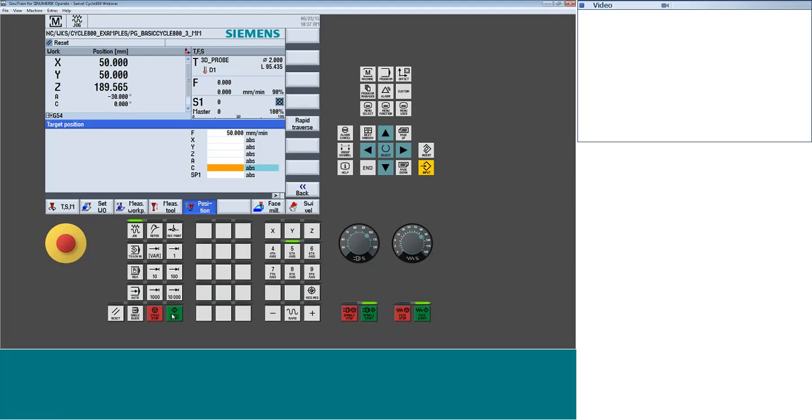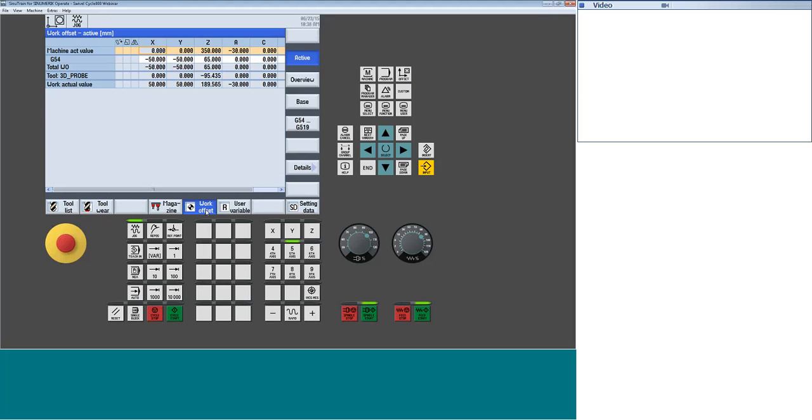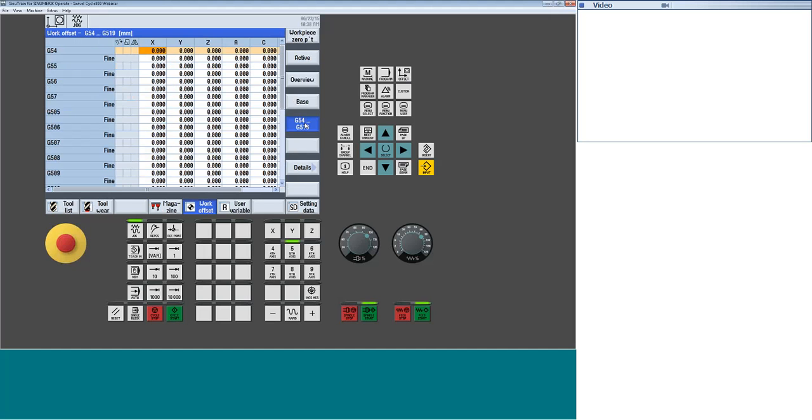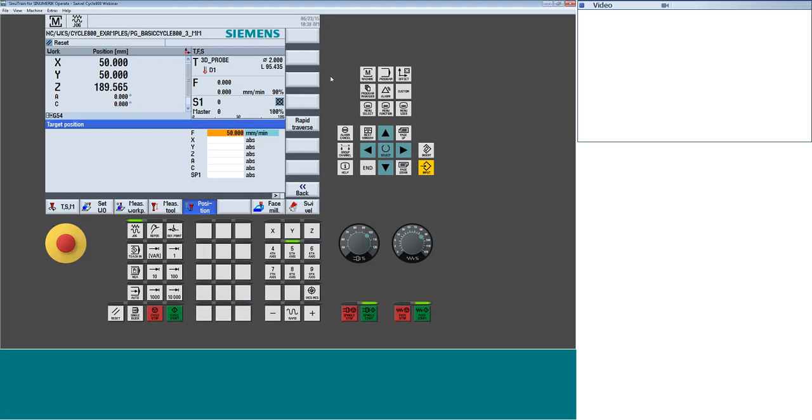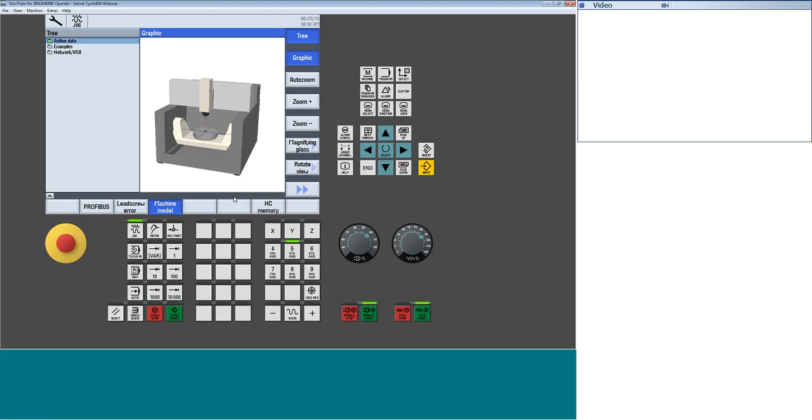What you can do is that value could have been written into my work coordinate system. If I go to my standard work coordinate system, right here as an A variable. If I tell it minus 30 degrees right there, now you see I have an A0 stipulated. So I'm at A0, yet if we look back, the machine's sitting at some angle.